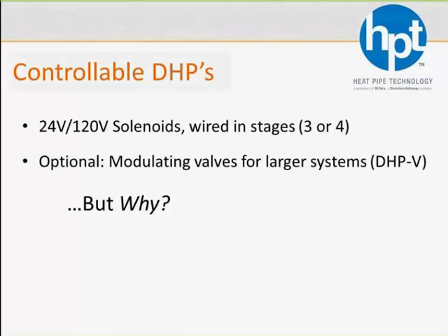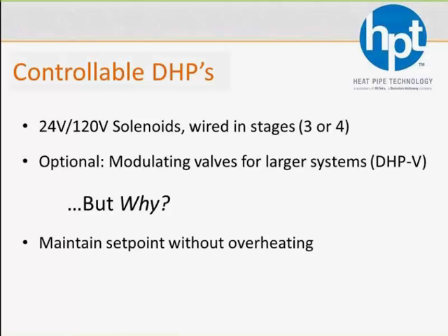Well, if there's a downside to the wraparound heat pipe, it's that you may not want that reheat. And, you know, the hotter it gets, the bigger the delta T, the more heat we're going to recover. So the more pre-cooling you get, and that's great, but the more reheat you get as well. And generally speaking, when it's the hottest outside, that's probably not when you want the most reheat. It's probably the opposite. So just simply putting control valves on there allows you to control that leaving air temp a lot better.